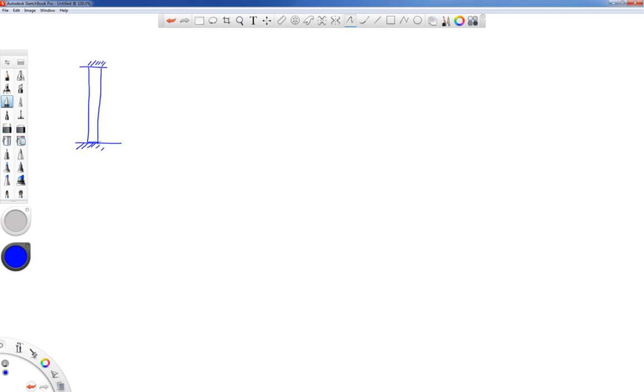So it's sitting there, but we put a wall on the bottom that it's resting on, and then we have something on the top that prevents it from expanding when it wants to. So here's our x direction again. We have our coefficient of thermal expansion, alpha, our cross-sectional area A. It's got some original length to it. And again, we're going to heat this up. We're going to increase the temperature.